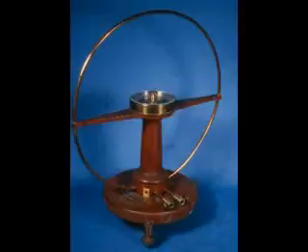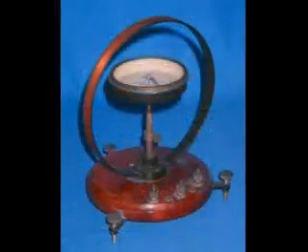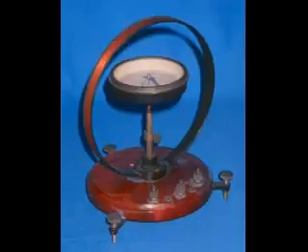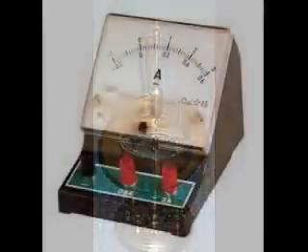They had to be used on a tabletop. The coil had to be turned so the windings were parallel with the magnetic field lines between north and south. When current would flow through the coil, the compass needle would deflect towards east and west. Such instruments were useful in their time, but have little place in the modern world except as proofs of concept and elementary experimental devices. They are highly susceptible to motion of any kind and to any kind of disturbance of the natural field of the Earth.